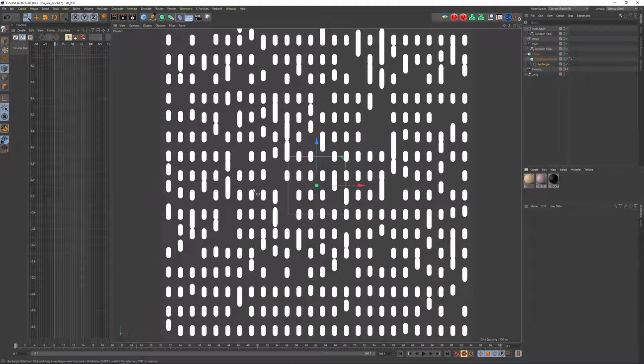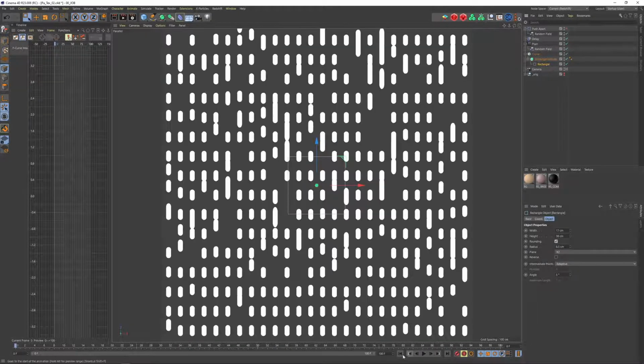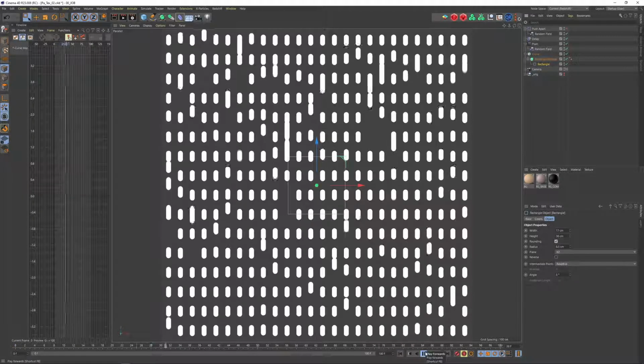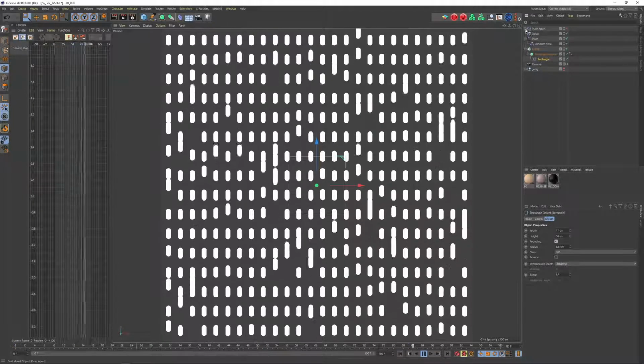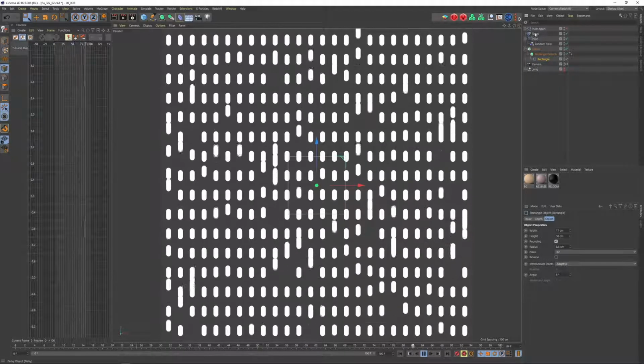Now I quickly want to give myself a second texture to be able to put that on the second part of my final design. So I am in the same scene and I copied everything and I replaced this sphere with a rectangle. So I'm having this type of rectangle, which is rounded. So you can see that's just the object, and I put it into the cloner. And let's press play. So overall, the setup is mostly the same. I tried to play around with some push-apart effects, but didn't use that at the end.